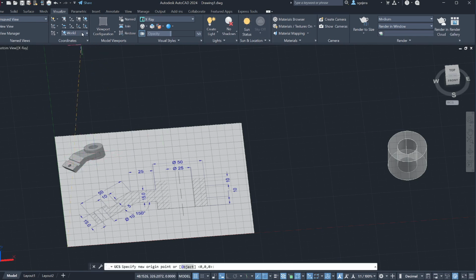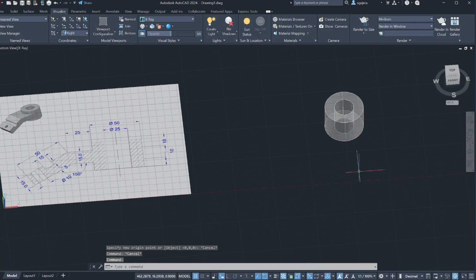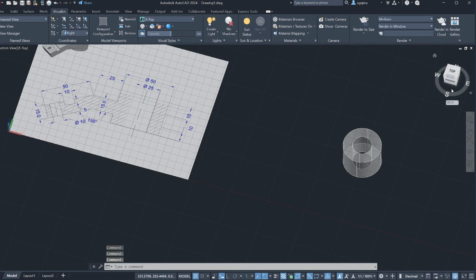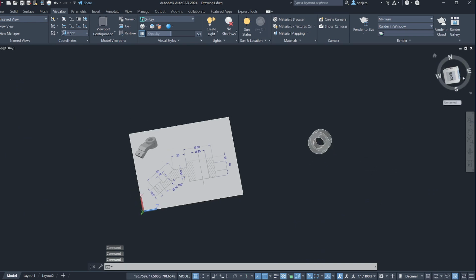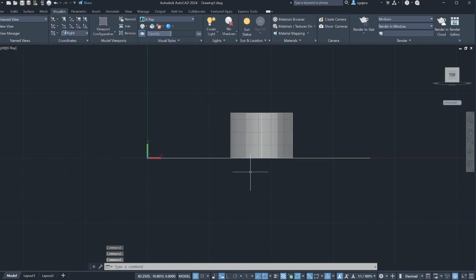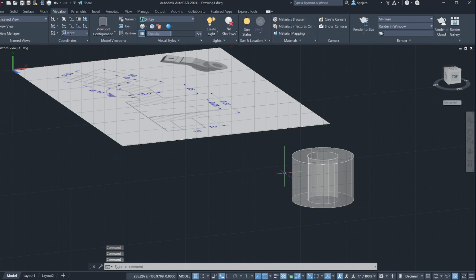So what we want is to use the right side view. Our new UCS will be at the right side view. If I look at the top, is this on the right side now? Yeah. My new XY would be this. I'm here. Right, something like that. So that's my new XY, located on this right side.